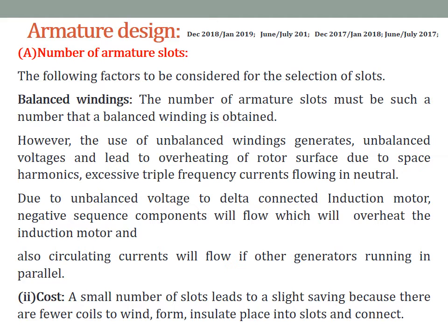What are the factors to be considered while selecting the number of armature slots? This is also an important topic. It has been asked many times. The following factors are to be considered for the selection of slots. First, balanced winding. The number of armature slots must be such that a balanced winding is obtained.